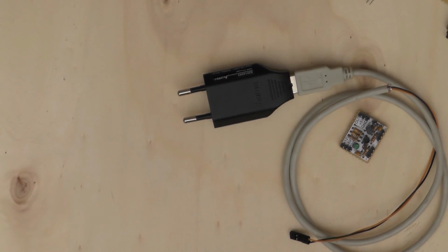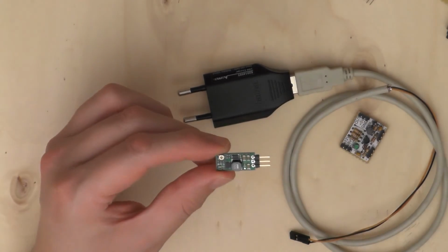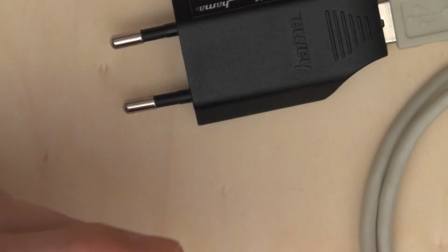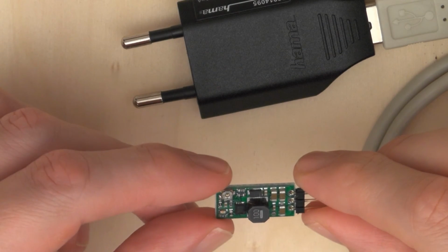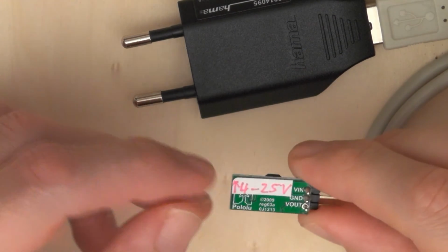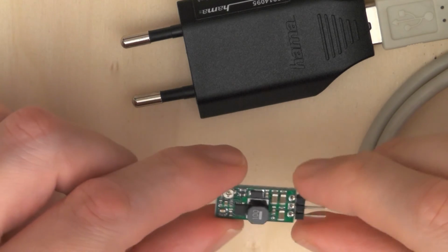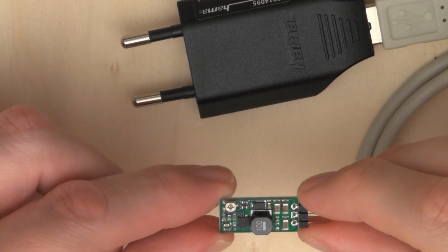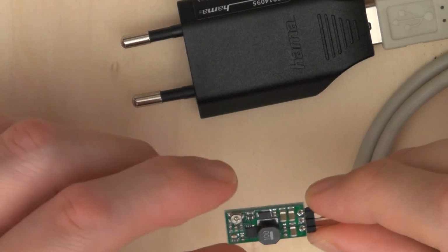Keep that together. And what would I use for a step-up converter? I've got these from Pololu. These are very, very nice little devices. Hang on. I paid about 13 euros for these. These step-up converters go from 4 to 25 volts. There's a little trimmer pot here, very nice for testing what happens if you change the voltage on the circuit. And yes, I'm going to show you the circuit as well in a moment.